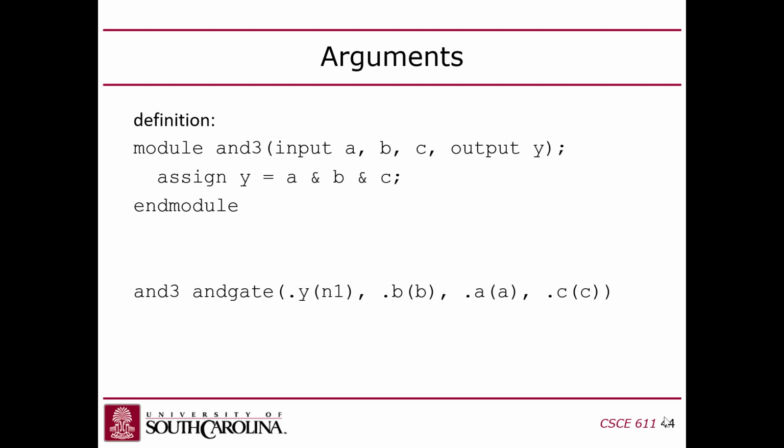And then this is the port map. So these are the inputs and outputs of the module. This is the port map, and this is how I connect. I put the dot A refers to A here, and then A refers to the signal inside here I want to connect to that input. Right? Now notice I deliberately put these in a different order. I connected the Y output first, and then I connected the B input second.